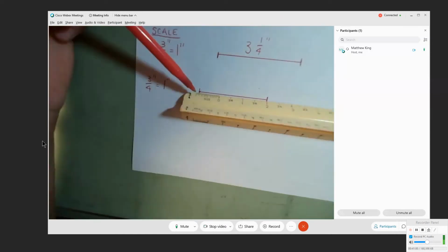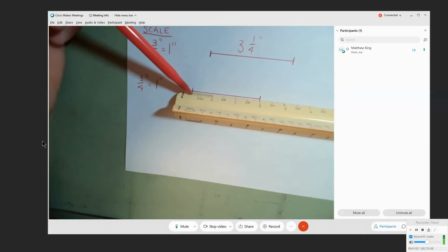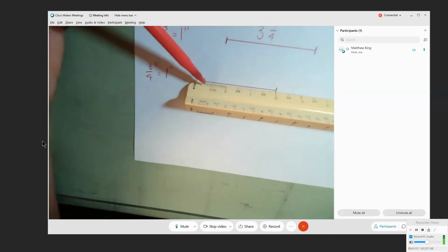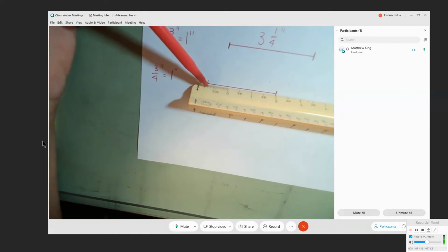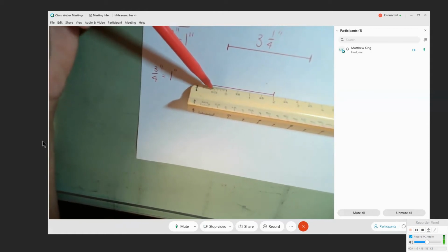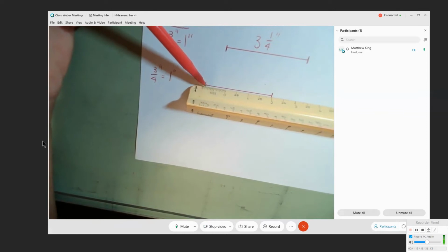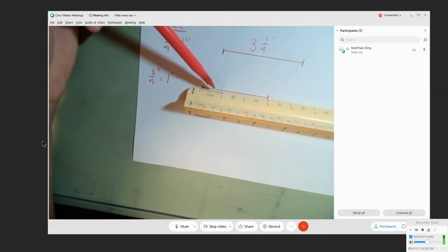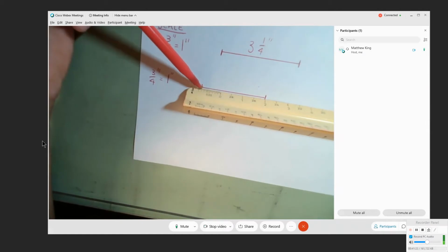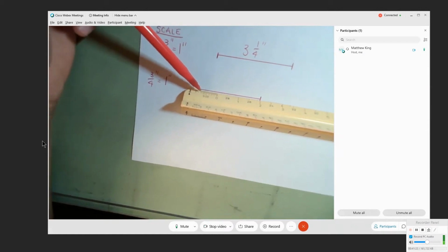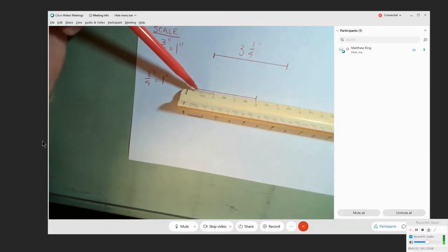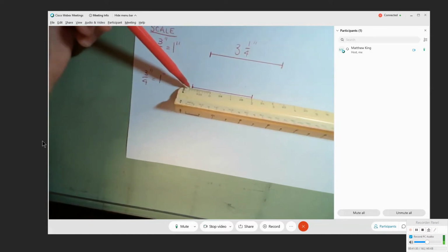And then I look over here, and I see it's right on this mark here, which I know is something big. So what is that? Well, that's something eighth, right? So if I count eighths, 1, 2, 3, 4, 5, 6, 7 eighths. If I want to take the long way over, I would go to the next shorter increments and count them. And I'm going to wind up with 14 sixteenths. That's a painful way to go there.